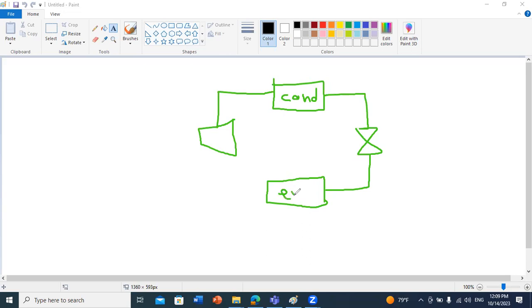This is why the place of your evaporator and condenser will be switched relative to a power plant cycle. In a power plant cycle, the evaporation takes place at the hot temperature, and the condensation takes place at the cold temperature.